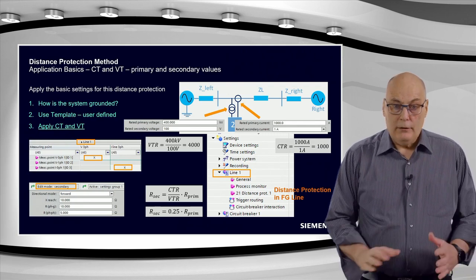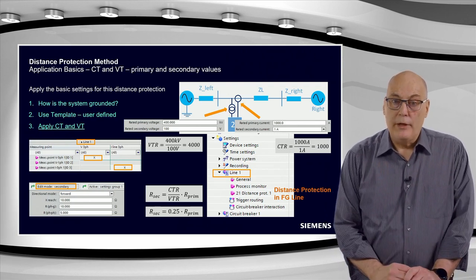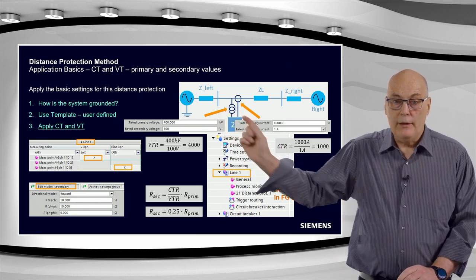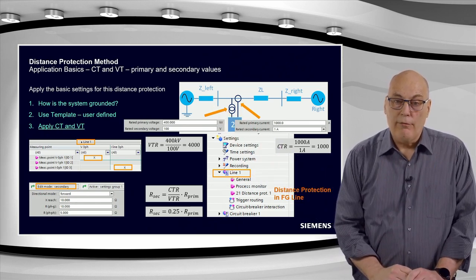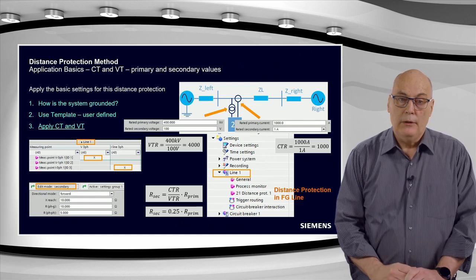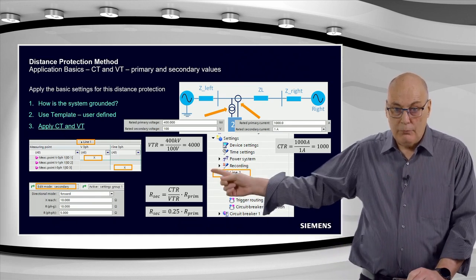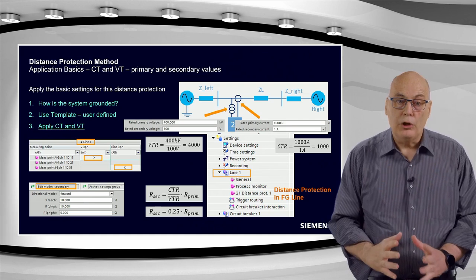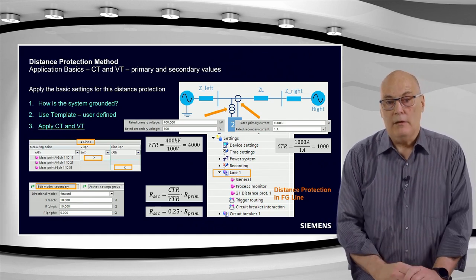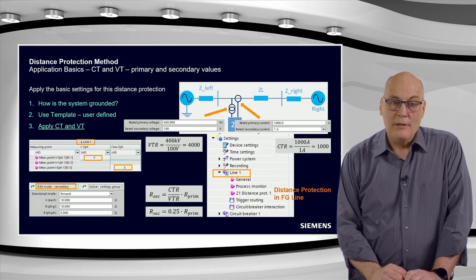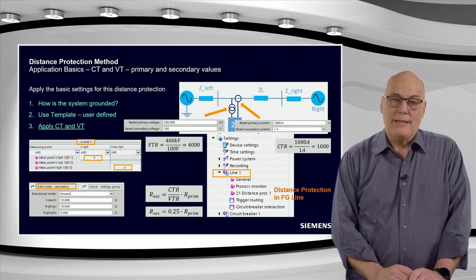Another aspect relating to that is obviously your instrument transformer, your CT-VT connection, as you see here. We need the data from the CT-VTs for the application, the ratio, and as mentioned in the first session, the conversion primary to secondary is important. You need to check, and you can in DIGSI, as you see in the bottom left hand corner there in the orange block, this time the setting there is applied as a secondary impedance.